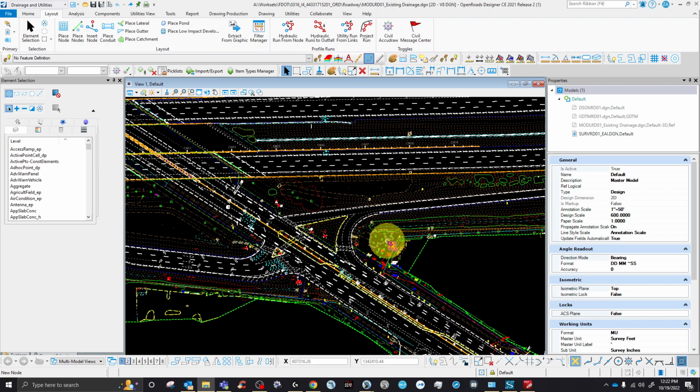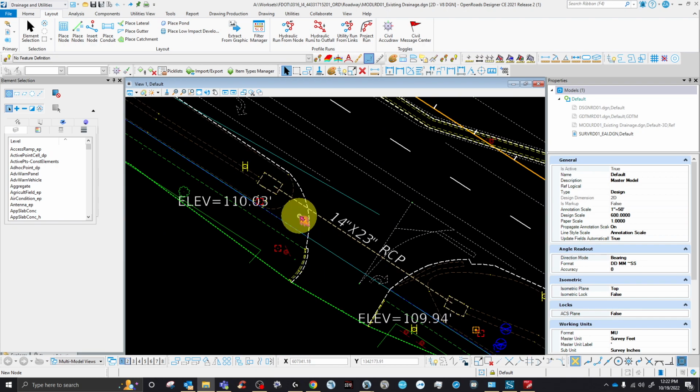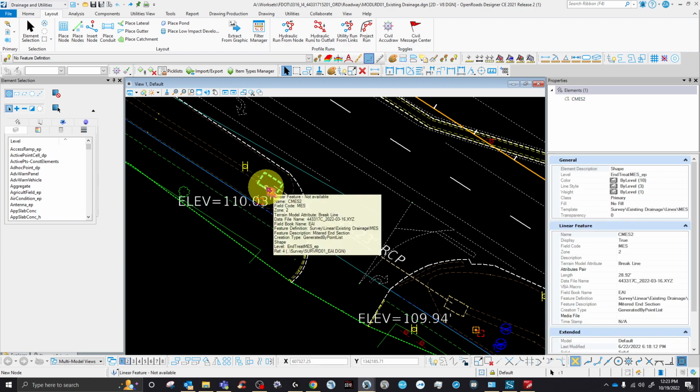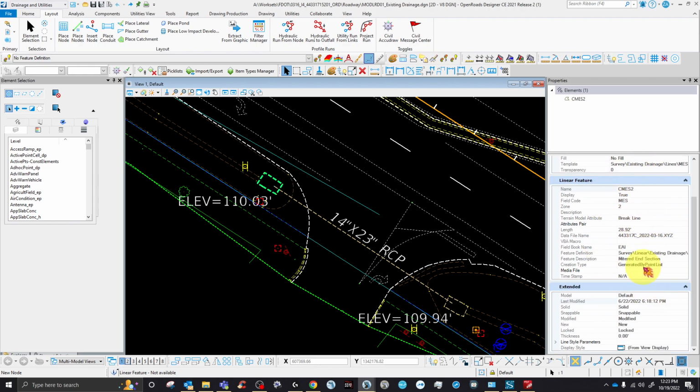Unfortunately, my survey doesn't have a lot of things. Like for example, and always need to pay attention with this, this is an advice for anyone. Whenever you get the file from the surveyor, make sure that they give you the thing that actually has everything in it, because it will make your life easy. Like for example here, he put the elevations for me. I don't know why he did that, because if you clicked on this, they should actually code it here, but I'm assuming they don't know how, so that's why they said let's put a text.